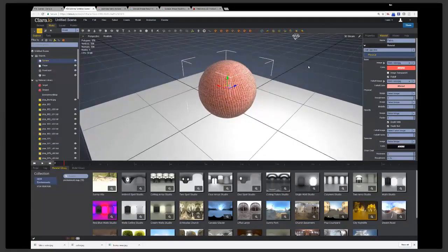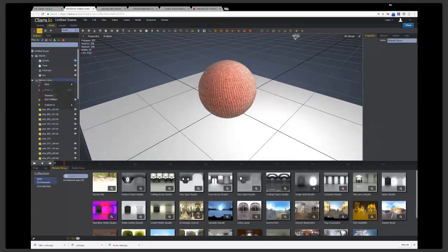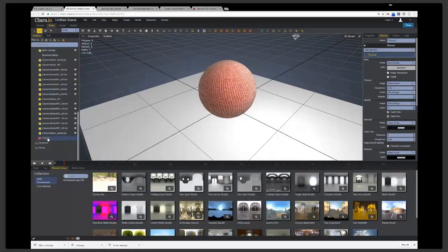I think the other one, why don't we set up gold? There's a lot of people that have to set up steel or gold for jewelry or other types of engineered objects. So I'll do that next. Let's just drag this on. They're actually super easy. I showed how to do them earlier. You basically put a physical material on. You set its metalness to 1.